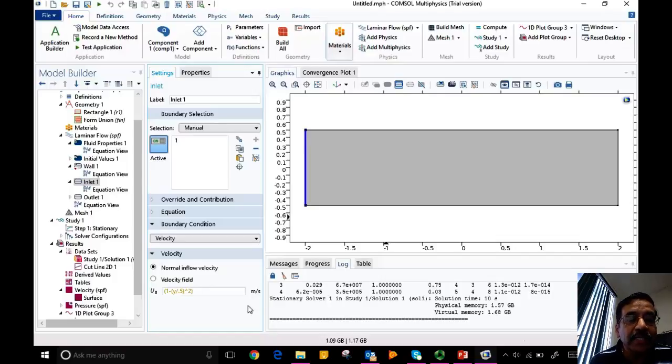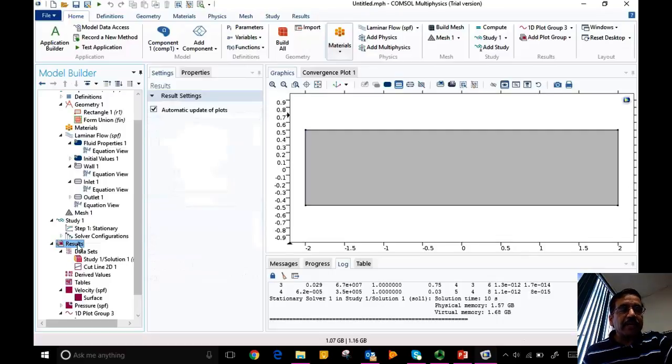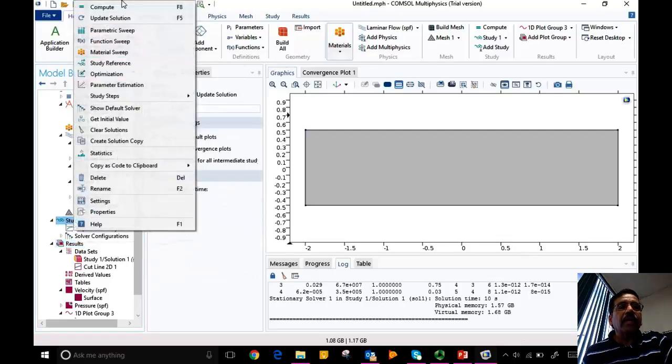I don't know whether you guys can see it, it's so tiny there, but it's essentially 1 minus, within parentheses, y divided by 0.5 whole squared. That goes from minus 0.5 to 0.5. The color is yellow, but it's a warning. If it is yellow, it's a warning that simply says that the units are not right. It's not in meters per second. But we can ignore that because we have not been using dimensions anywhere. We're just using a dimensionless form. Okay, so that's it. And the mesh will automatically remesh if I just say go and compute.